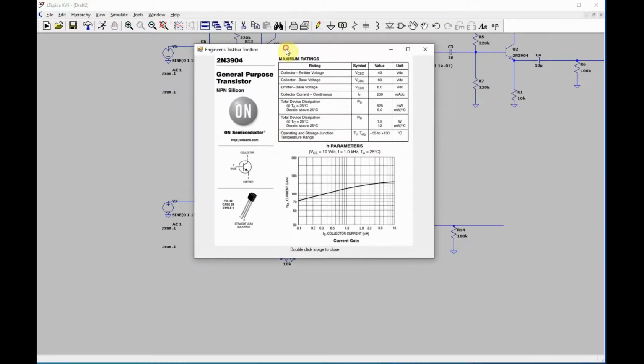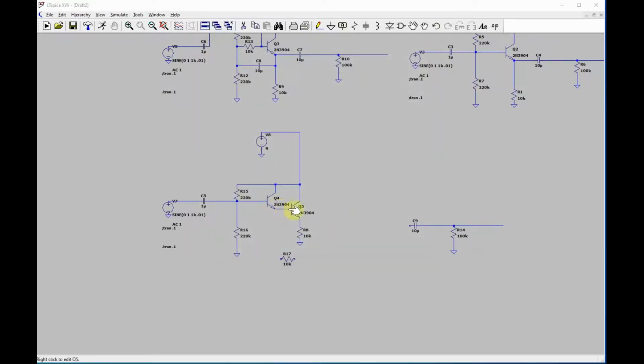Again, my trusty calculator. You can see, depending on the collector current, the HFE depends on that. You see this on different sheets and so forth. So running this into here, there's not much current going through there. So you can hook this up and tie the emitters together, and that kind of fools it. It gets more current going through here, and it sort of raises the HFE a little bit. They work better that way, although I've admitted this before and it does work fine.